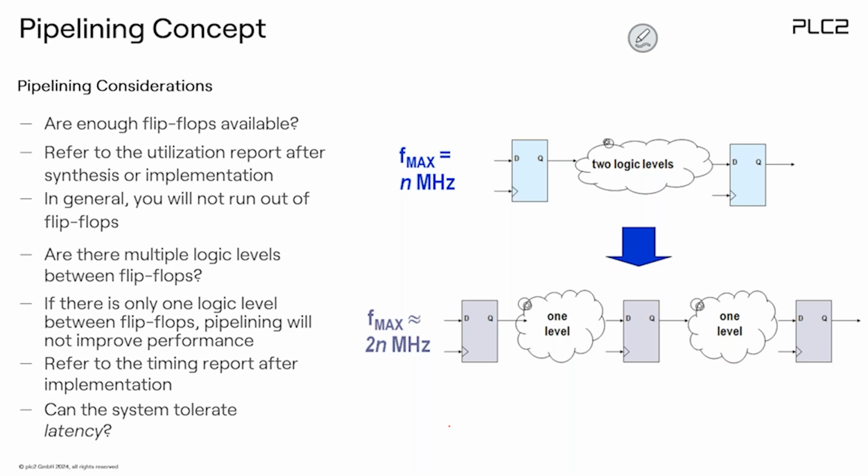That's very simple. The pipeline basically means you have a clock here, and if I use one clock, I have just one period to run through this logic. This means, let's assume I have a very big delay here, 10 nanoseconds. Ignoring clock output and setup time, the frequency would be 100 MHz, because a 10 nanosecond period is the minimum.